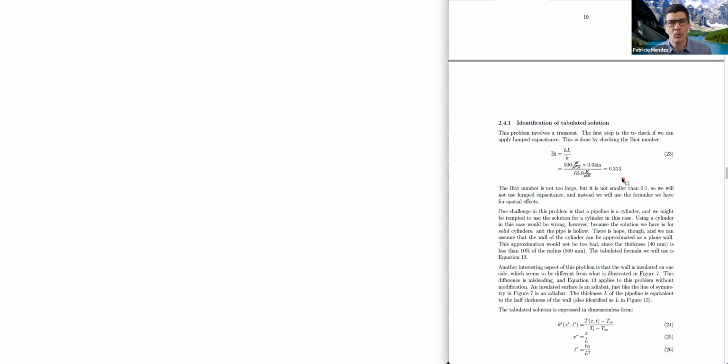If the Biot number was 10 to the 3, you know pretty much everything about it, because the surface of the pipe is going to be at the temperature of the fluid, and we have the coefficients already there. This problem hit us just where it hurts, more or less 1, where you cannot say this is one extreme or the other extreme, but this is on purpose, right?